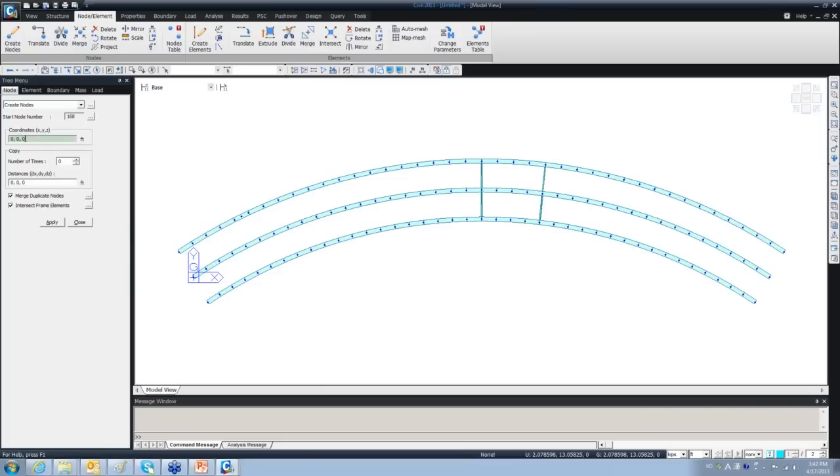I use the 0, 0, but instead I know that it's going to be 15 feet above the point of origin, or away from the center of the center girder. So X will be 0, Y will be 15, and Z will be 0. This is my first point, and it shows up here. Then the next point will be 200, 15, and 0. Third point will be 100, 45 and 0, apply.